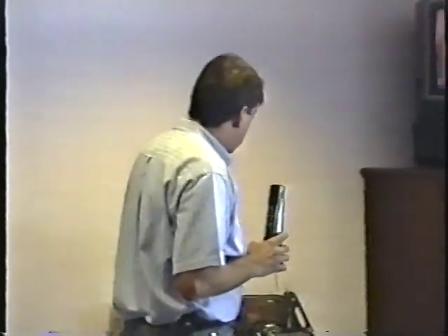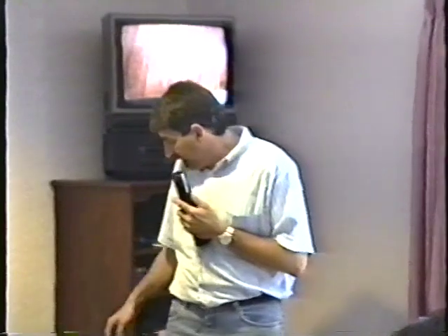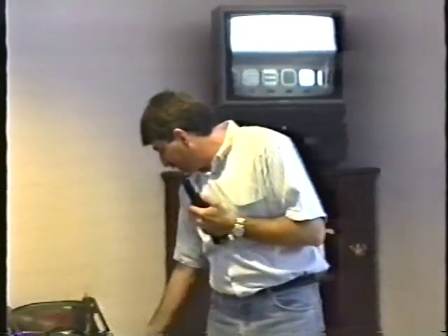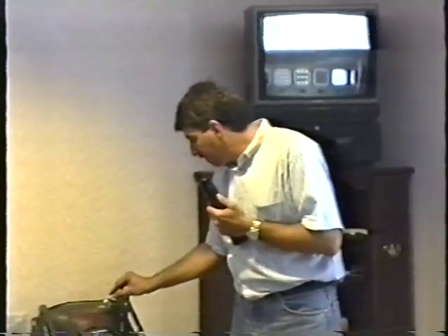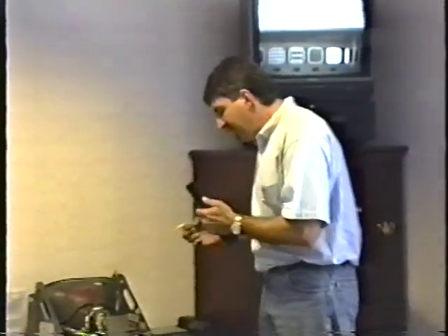I've even gotten shocked off the thing when it's been plugged in because I didn't realize it was plugged in, and I go to grab the thing. Gosh! So, you know, it's not something that'll kill you. You just have to be kind of careful when you go to reconnect it that you redischarge it. So you redischarge it like that, and then using the grounded screwdriver, get both of those little fingers in there.